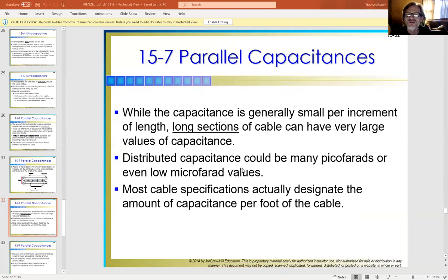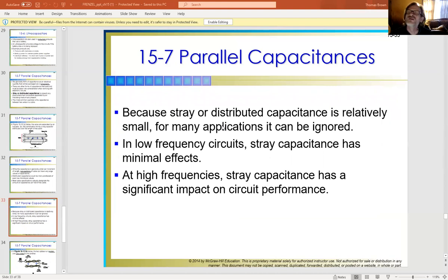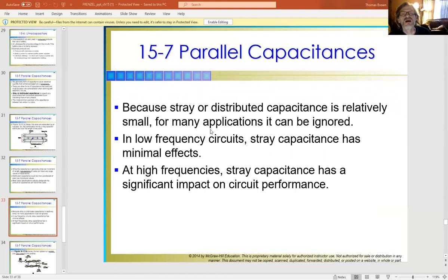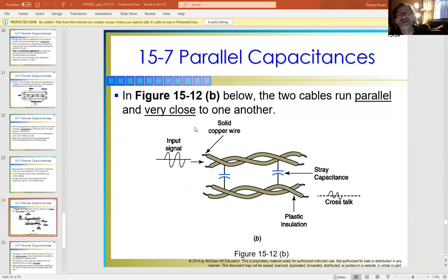It's a cheap and easy style capacitor, but this effect can happen, and if you're not careful, sometimes you can actually introduce a parallel capacitive effect into a circuit without realizing it, and then sit there and go, "Oh, what the heck is wrong?" And it's like, "Well, you made a capacitor." It's just something to think about as a technician. You run into some strange things out there. But in this case, you see it stranded together like that.